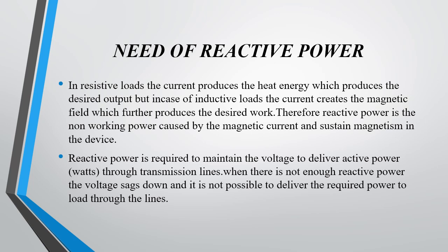Then let's see what's the need of reactive power. In resistive loads, the current produces the heat energy which produces the desired output, but in case of inductive loads, the current creates the magnetic field which further produces the desired work. Therefore, reactive power is the non-working power caused by the magnetic current and sustained magnetism in the device.